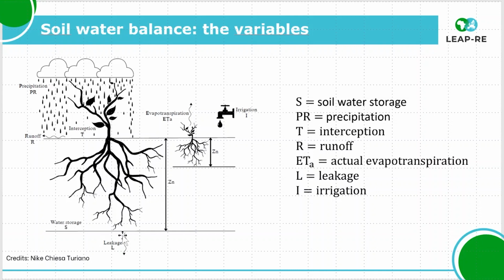So depending on these hydrological fluxes entering the control volume, you can evaluate the crop evapotranspiration, so the amount of water needed to grow and to allow the photosynthesis process. At the same time, knowing the evapotranspiration demand, you're able to assess whether this can be met by soil moisture alone, or if you need to consider some irrigation volume.